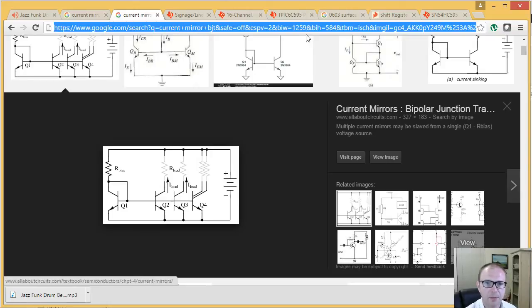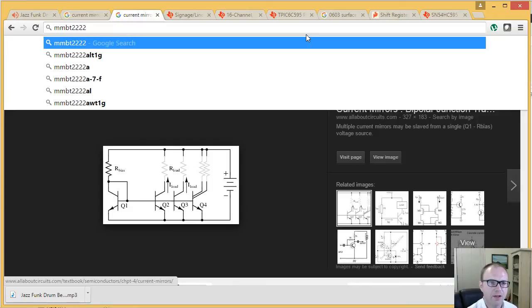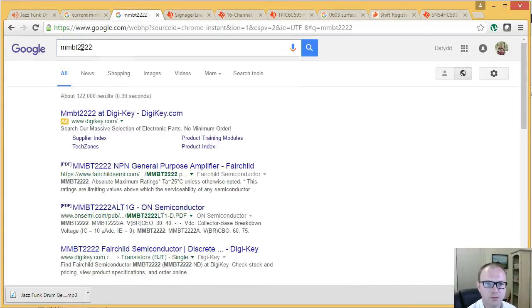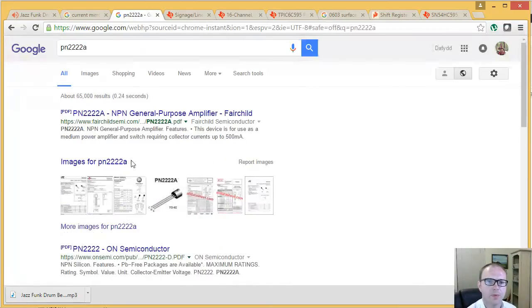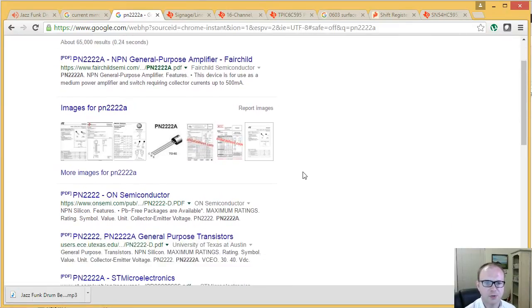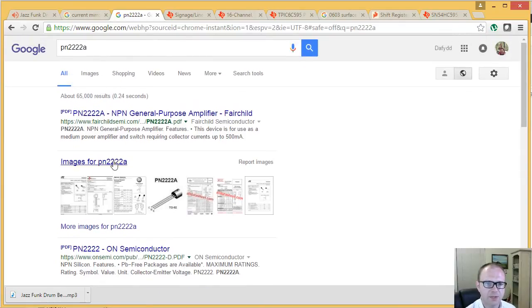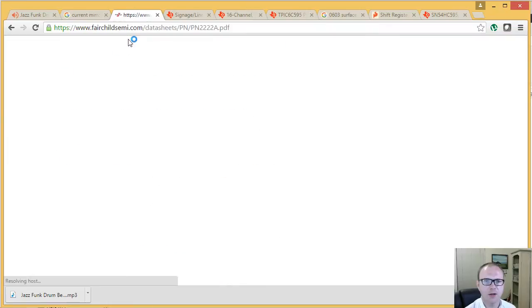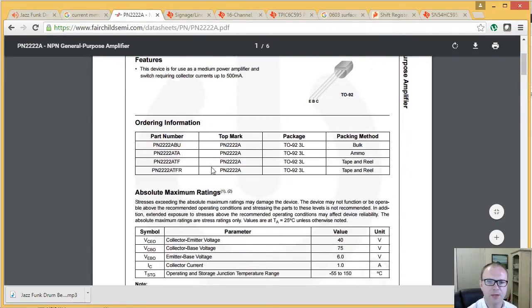And my transistor of choice for this kind of effort is the old 2222. They used to be called PN2222s. These things are as cheap as chips. Because I'm just using one per LED, they're almost cheaper than the LED. To give you an example, let me put up the datasheet real quick, and then we'll have a quick look on eBay to show how cheap it can be.